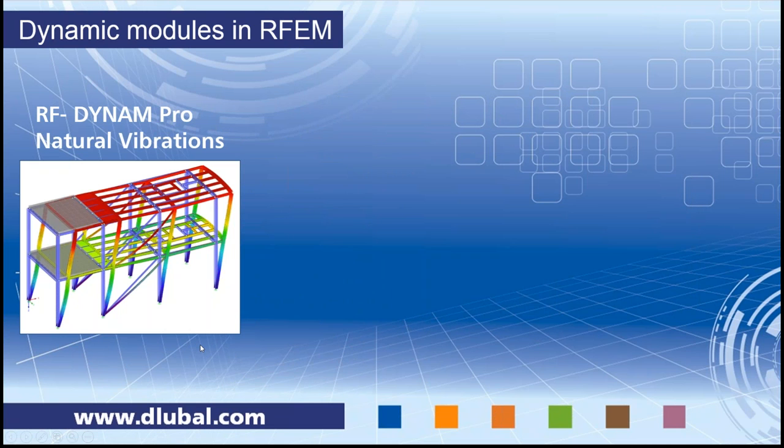This is what you always need, and it performs an analysis of frequency and mode shapes for members, surfaces, and solid models. You can directly import masses from load cases. You can build combination of masses in so-called mass combinations, and you can import stiffness modifications, axial forces, failing or deactivated members, or stiffnesses from RF concrete as initial conditions. So these are just a few examples. We have 4 eigenvalue solvers available, which I explain more in detail when we go through the example.